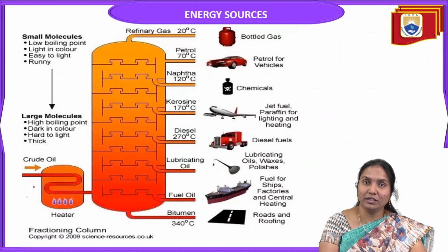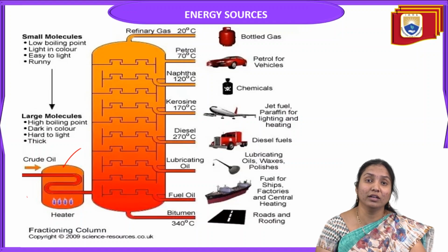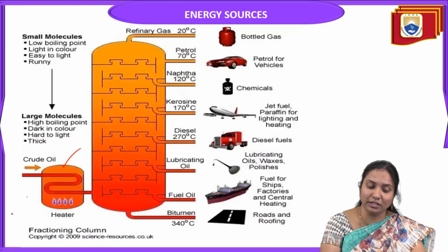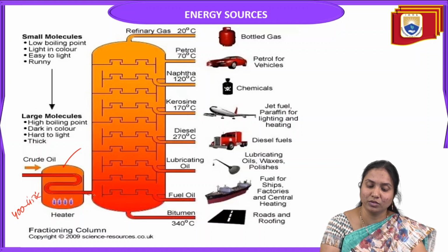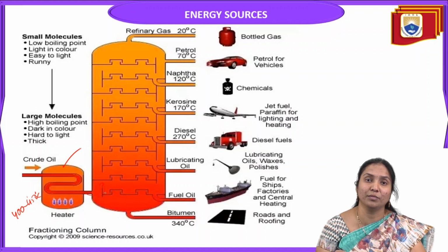So you see clearly it shows that this crude petroleum, after removing impurities, solid impurities, water and sulfur, is heated in this heater, maintaining a temperature range of 400 to 450 degrees centigrade. In this case it produces vapors. These vapors are allowed into this large stable tank.